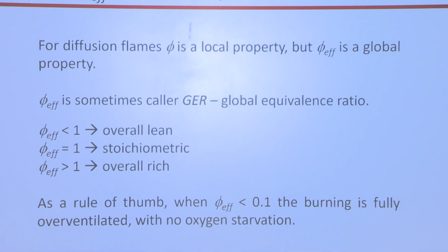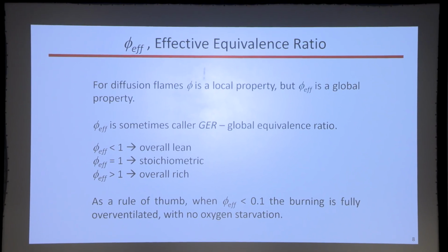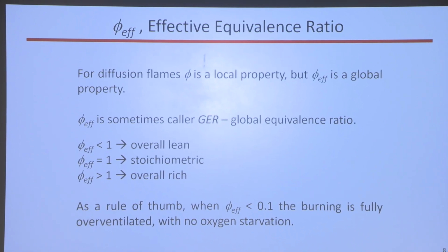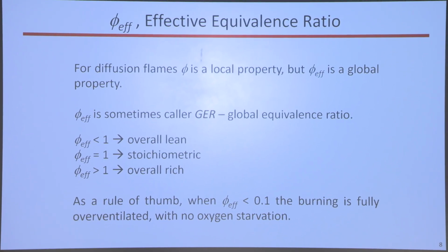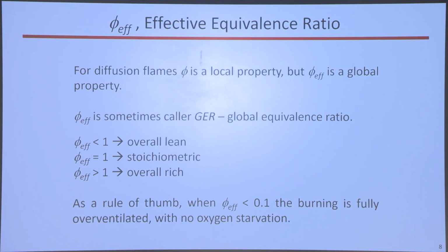So when you do these tests, you want to make sure that the flame went out because of the agent and that it had plenty of oxygen, that you weren't starving it for oxygen. And so it's important when you do these tests to do the math and check that your flow rate of air was sufficient, that that's not the reason the flame went out.